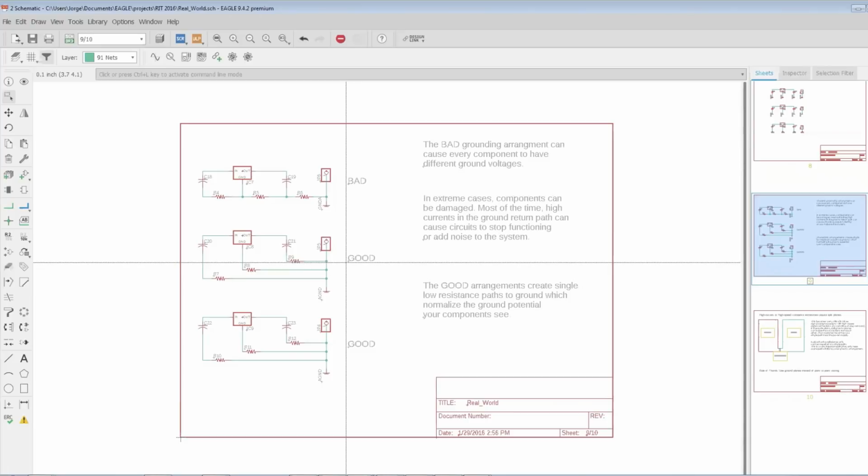Impedance is simply the relationship between a voltage and current in a conductor through a component. Okay? That relationship can be very complex, especially if you have an inductor or a capacitor. You're going to have phase shifting. You obviously have a frequency dependence. So impedance is more general than just resistance. Okay, so we're going to be talking the rest of this webinar series as we do them. We're going to be talking about impedance. Keep that in mind. Relationship between voltage and current.